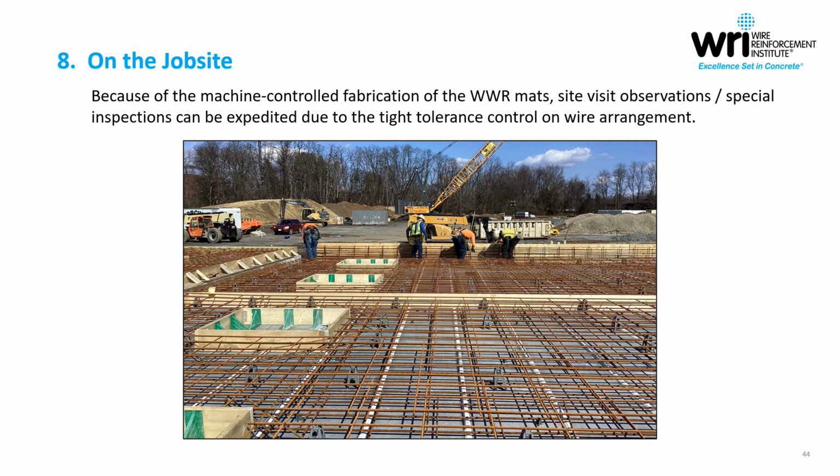We're going to wrap up just with some photos on the job site. Because of the machine-controlled fabrication of the mats, your construction administration, your CA services, which of course would include site visit observations, as well as the special inspector on the job, observing this material, pulling a tape, it really goes quickly because these mats are produced on machines. These are not manually welded mats.